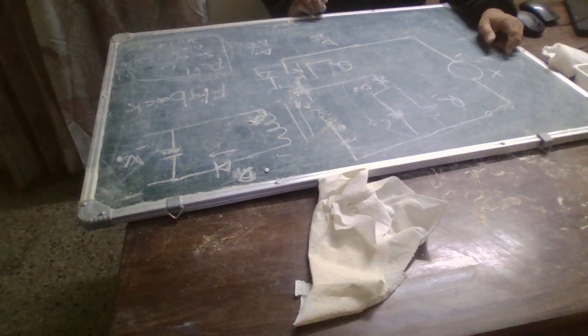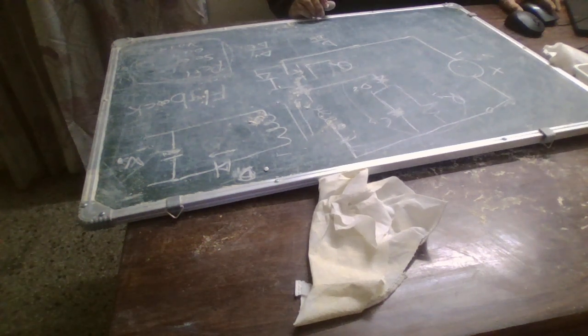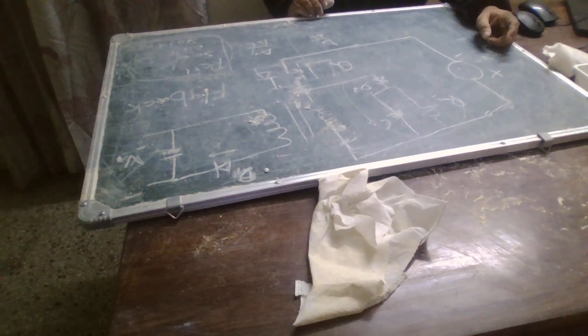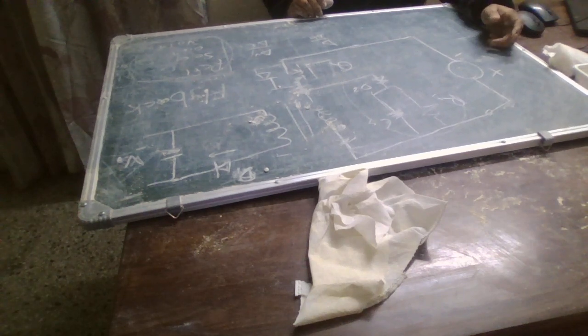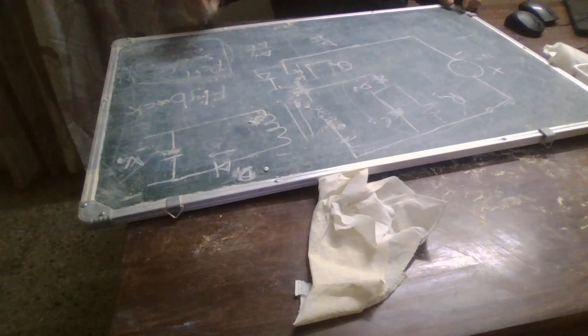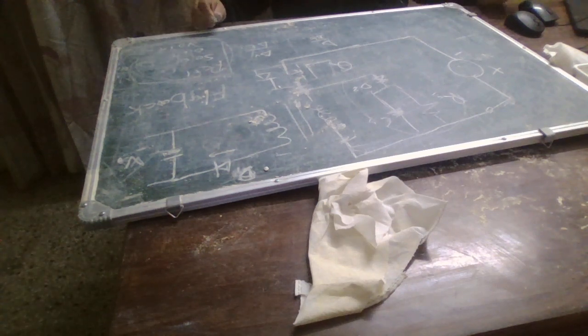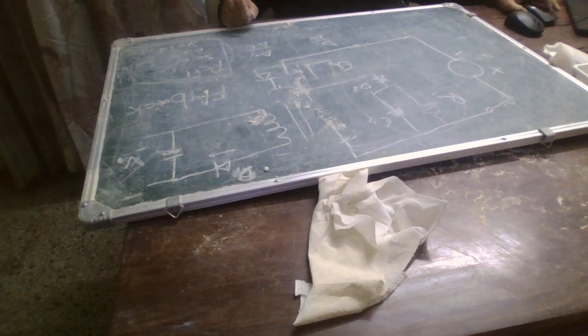That's why this is known as a flyback converter or a flyback transformer, because it is going to transfer the energy stored in the primary of the transformer to the secondary through the flyback action. Here we are getting a flyback overshoot because of the reflected secondary output voltage, and it is going to clamp the primary winding voltage to a safer level, that's again through the flyback action.